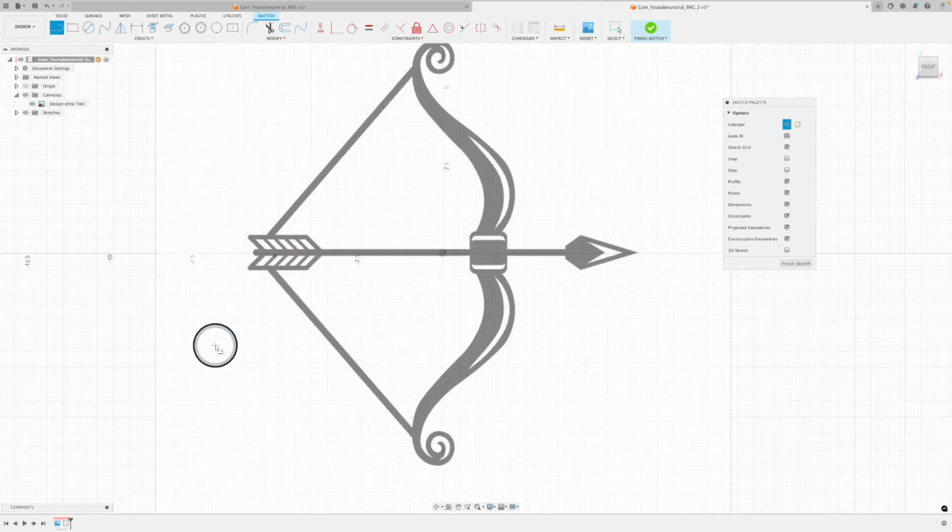which you can also find under Create, but it usually is in the options here. Then you just draw a line that is a bit longer than your arrow. Make sure that it's not skewed to some kind of degrees, but at 0 degrees, so it's just horizontal. Then you just left click to fixate it, and then click on this green check mark to finalize this one line. Then hit escape, so you're not in the line mode anymore.